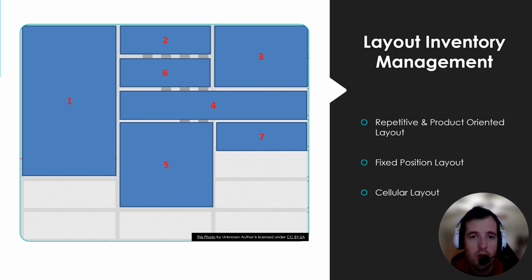For areas focused on component production, like motor or electronics assembly, Tesla uses a cellular layout. The cellular layout is a setup where workstations are arranged in cells, allowing specific components to be produced and tested independently before being assembled into the main product. This approach helps Tesla reduce production time and improve quality control before components are integrated into the larger product. A cellular layout also allows an organization to adapt to changes in production demand, as they are able to reassign resources within their cells or even reconfigure cells for different tasks.